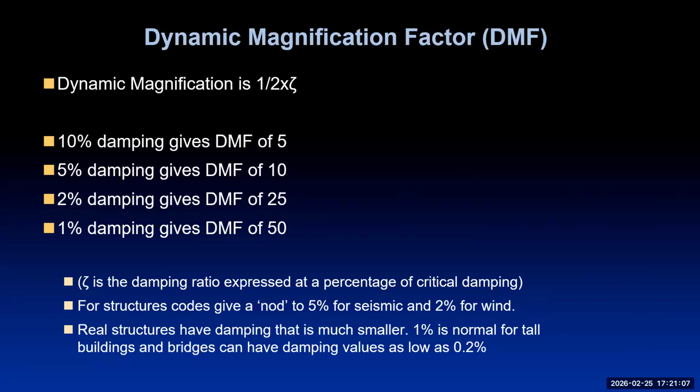And if you look at the size of the minarets, they're all the same thing. These are the towers that sit on the corners of the mosques where they do the call to prayer. And those displaced exponentially with probably just those 3 cycles. And it basically took out hundreds of these specific structures that had very low damping because by their nature, they have to. They had the right height to put them right at 3 hertz and they got wiped out. So it's really interesting to understand these principles of structural dynamics and see how they play out in structures.